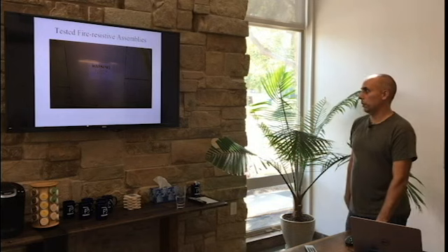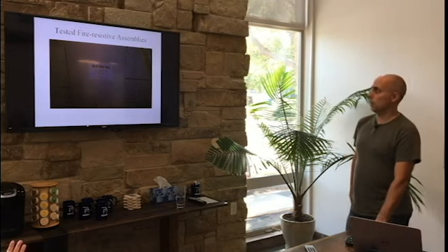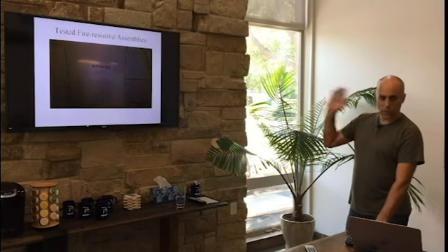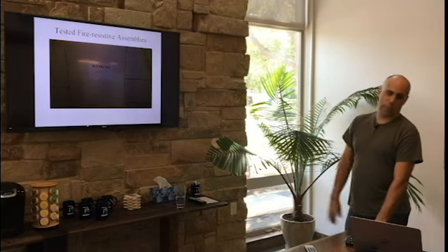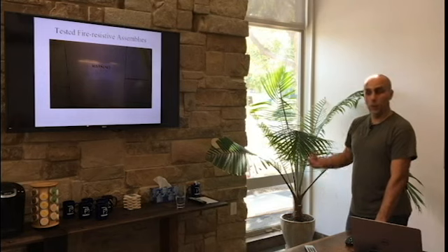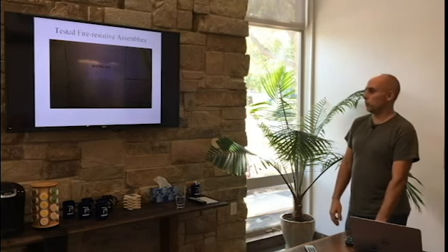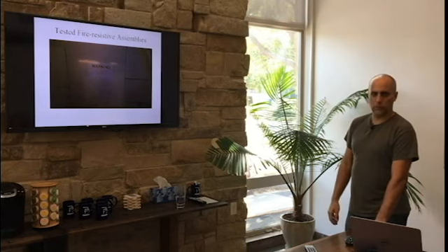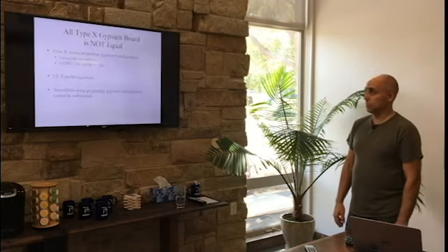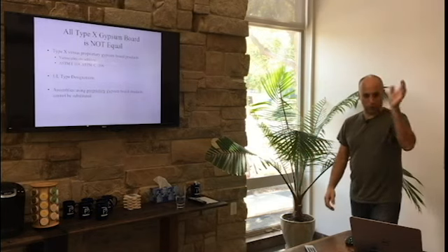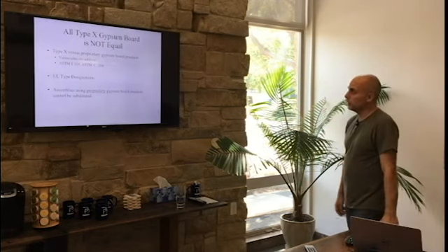Well, here's an example of one that a particular surveyor or inspector said, no, I want them all sealed with fire caulk. So they used a product that was not in the assembly and didn't tape and float or cover any of the screw heads with what was required. So this in no way meets the assembly as described, even though the inspector said, I want it that way. Well, he was telling them to do something that was never tested. They never tested it with fire sealant between all the joints.